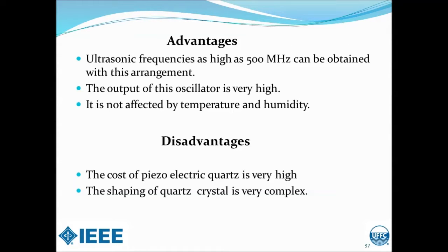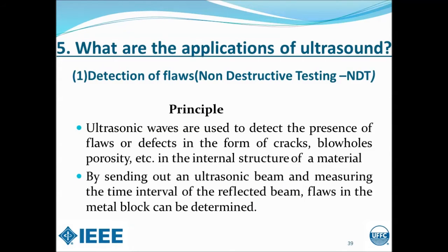Advantages are that the ultrasonic frequencies go as high as 500 MHz. The output of the oscillator is also very high, and it is not affected by temperature or humidity. The disadvantages are that the cost of a piezoelectric quartz is very high, and shaping the quartz crystal can be very complex. What are the applications of ultrasound?